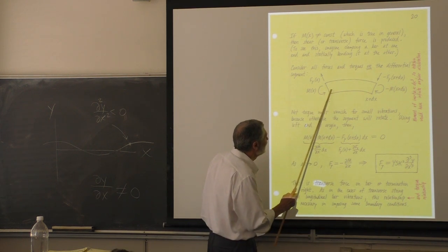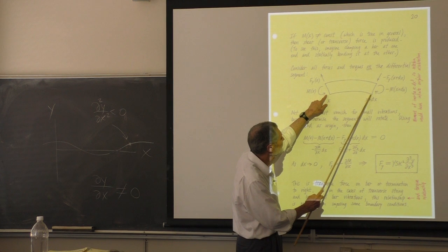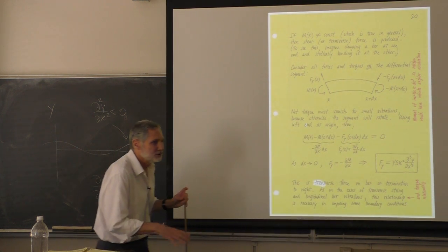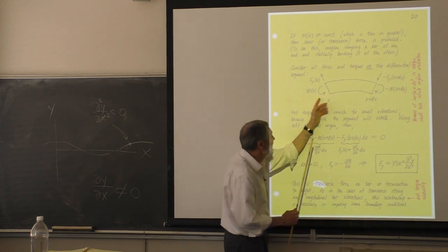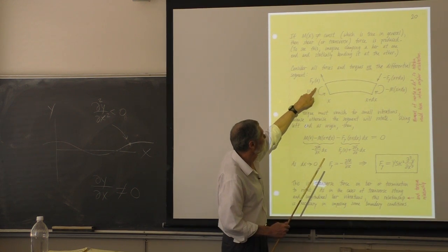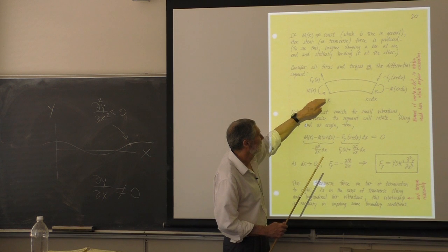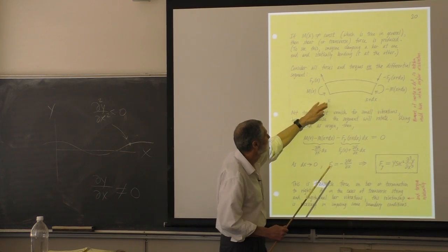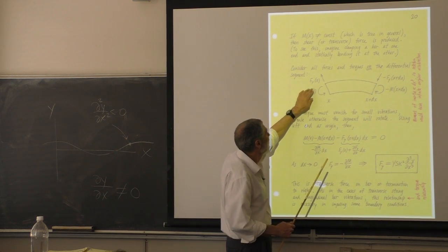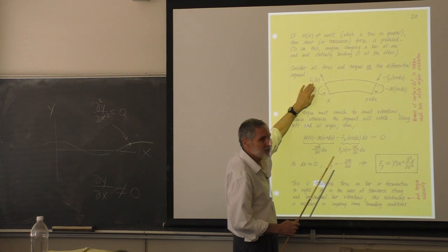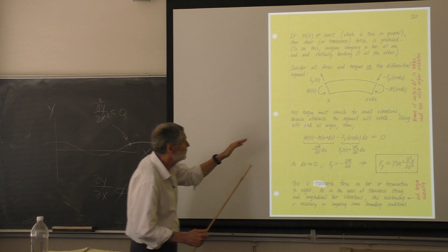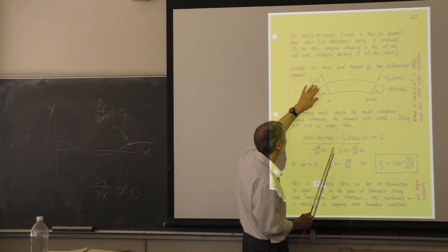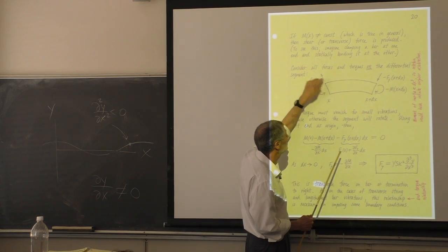First of all, we take an element, this is from x to x plus dx, and we look at all the forces and torques on that element. So at x here, there's going to be, in general, a torque. Now, I'm not saying that the torque is necessarily in this direction. I'm just saying that's the positive direction for a torque. Okay, and it'll have some value. We have to allow for some transverse force. We know that there has to be transverse forces here. So we're going to call this F sub y transverse at this location x, and that's the positive direction.